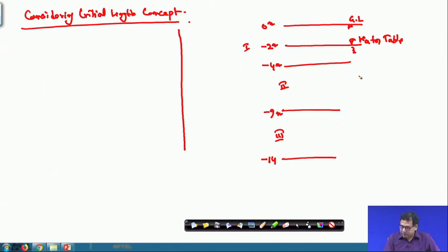So, I will take the critical length divided by d as 15, because that is the top portion where this is the loose sand, this is the medium sand. So if I take this as 15, your critical length is 15 into 0.35. So that is equal to 5.25. Okay. So, that is the critical length.